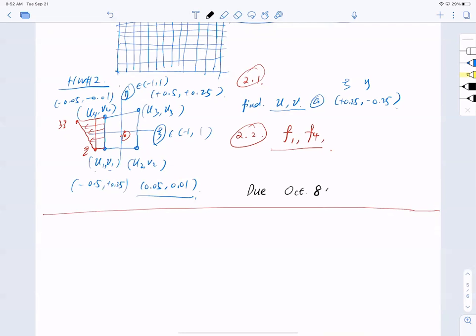And now if there's a bonus point, you don't have to do this, but it's up to you. If this is the bonus one, what if this is parabolic, and you probably have to figure out a parabolic interpolation yourself? If Q is a function of the local coordinate s and is parabolic, meaning second order, show F1, F4. Also show Q at half L, if the length is L. Very simple, Q at half L.